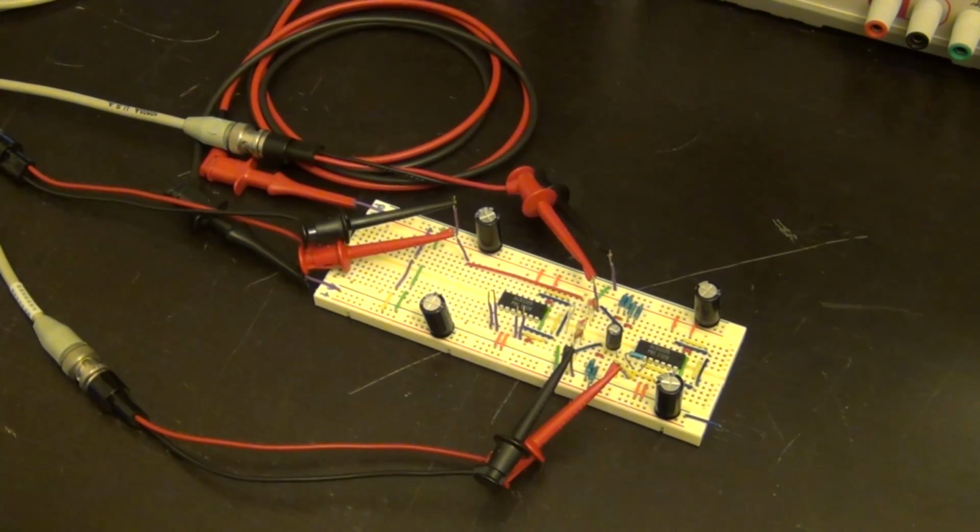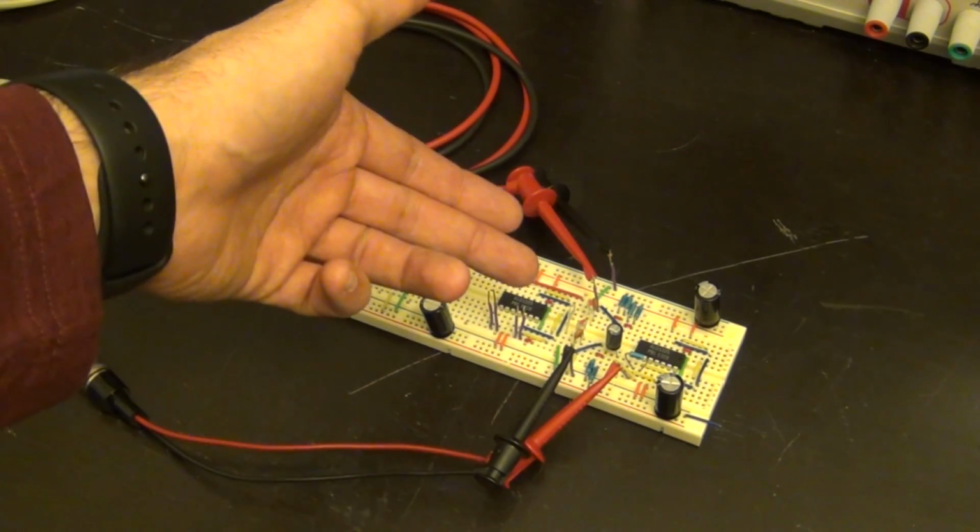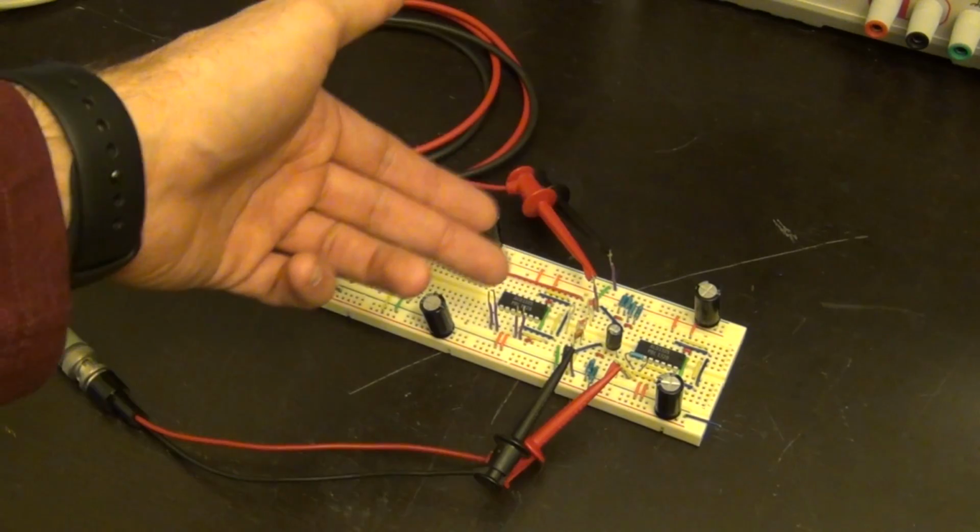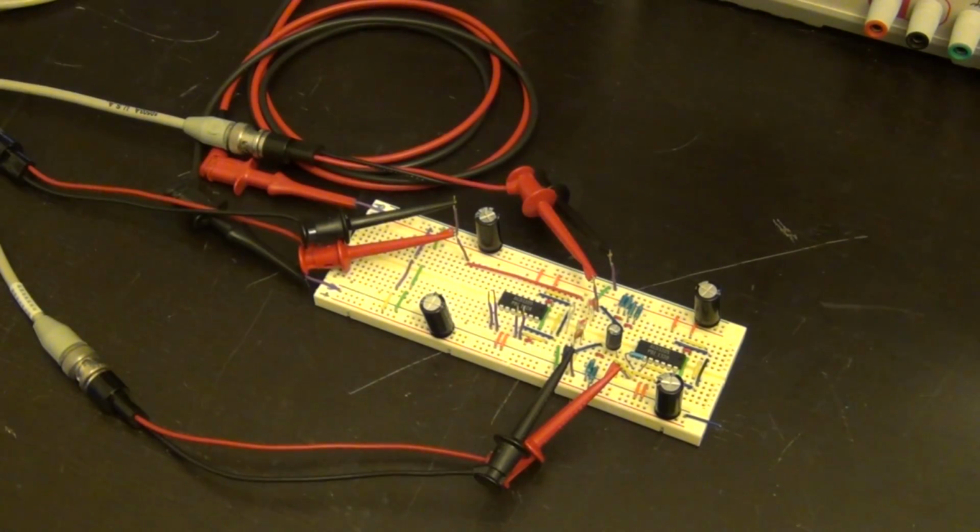And now finally we have put a signal through our transmitter, our LED essentially, and then we have the two photodetectors simultaneously receiving the signal with roughly the same amplitude, and as we said before, one to the resistor and one to the transimpedance amplifier. So now we can go on the oscilloscope, take a look at the output waveform from the two different mechanisms of generating a voltage, and then we can finally measure the bandwidth, and that's where the difference is going to be, and we will explain it on the oscilloscope.